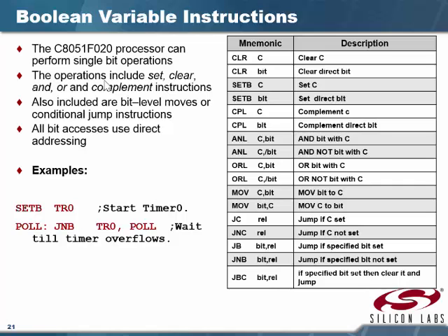It's actually not part of going through the instructions, but it's just something you can do. You can put the slash, the little slanty thing, in front of P1.1, which means invert it before you do the AND. Right there. So you've got that there. And you can do the same thing with the OR right there. And then we can move a bit by bit. This should also mean variable and bit instructions right there. Then the last four are jump instructions, and these are conditional jumps.